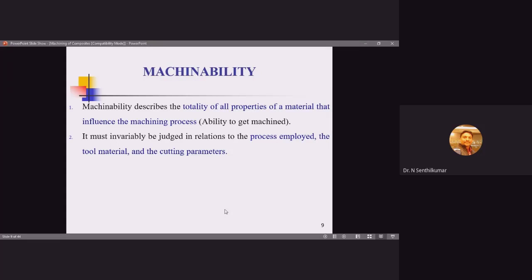Because during composite machining, we cannot consider high cutting speeds because chipping of the tool will occur. Because there will be a soft matrix, and suddenly a reinforcement phase will come in contact with the cutting tool. So that's the problem in composites. Okay, are you able to understand? While machining, the soft metal matrix will be easy for the cutting tool to remove. But suddenly, if reinforcement particles like boron carbide or boron nitride come in contact with the cutting tool, because of that high speed, chipping of the tool will occur. So, yes, low speed or a moderate speed is recommended for machining.